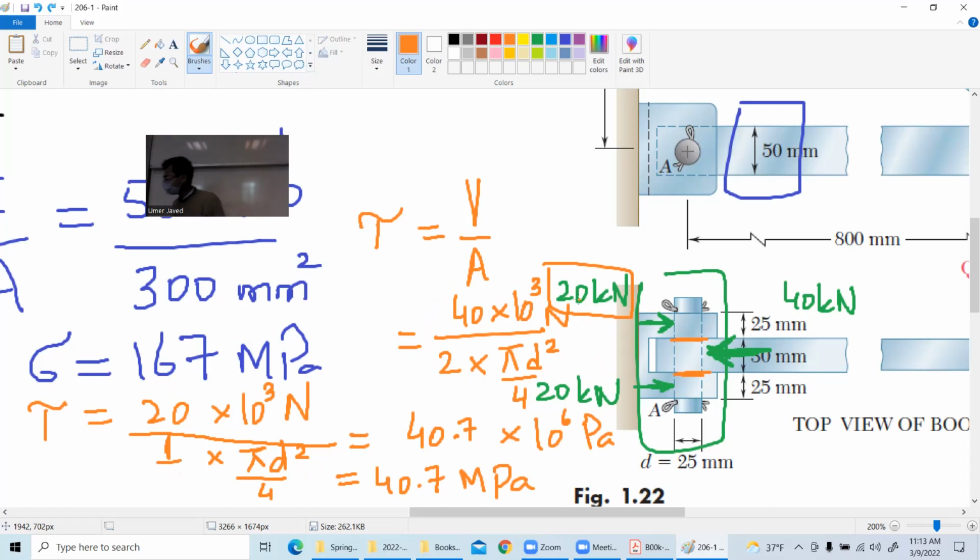So we are assuming that the pin is breaking right from the top part or the middle part. Why can't it break from the center portion? Oh, why it cannot break from the center portion? They will. Any of the center part. It's like 30 millimeters, so why can't it break? You're right. This is correct. We will actually work on that as well. So that's the bearing stress.